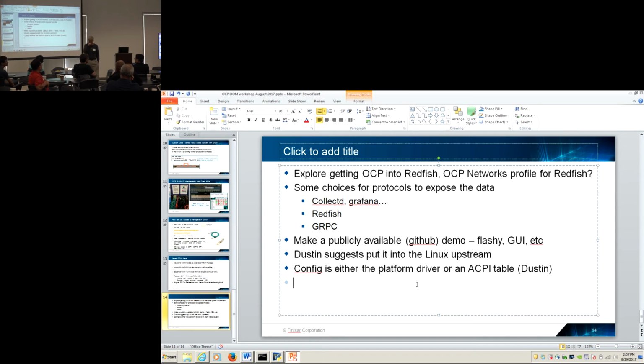I'll just point out that having Python in between the ASIC, CPU, and SFP cage can be problematic in the same way, because you don't really want that feedback loop going through user space, or at least not through a Python process. There is some need for the kernel itself to associate the SFP cage with a netdev. If any link bring-up tasks require knowledge of the SFP cage and knowledge of the SDK, this approach is not exactly in the right spot to transfer that information. So there are cases where you need kernel access to some of this data, and the driver we have actually has the MAC interface to allow access to the EEPROM as well. That came from you guys.